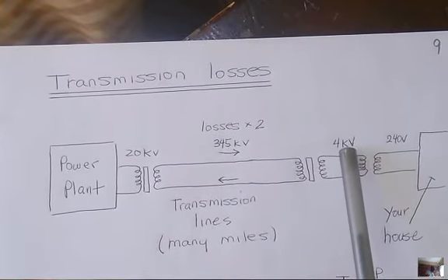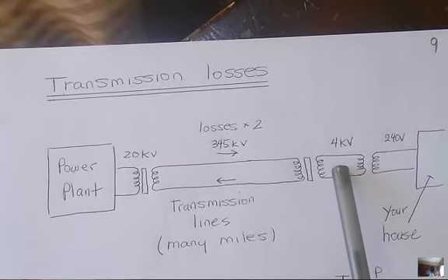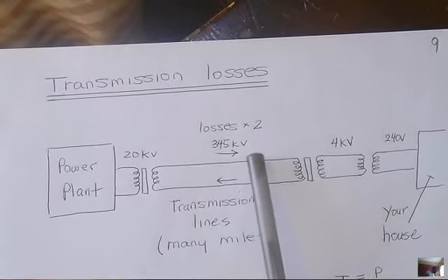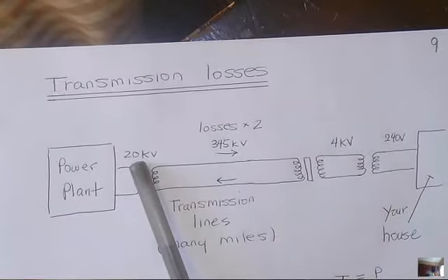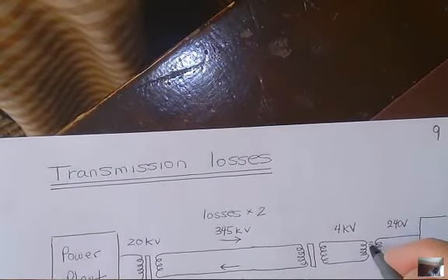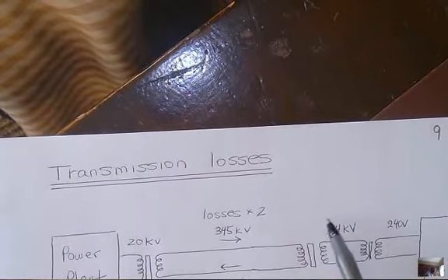This is in the town that you live in, different areas of the town. They probably have maybe 5, 6 of these in a typical Bergen County town. There's a step-down transformer that takes it from 345 kilovolts back down, even below where it started at the power plant, to 4 kilovolts. And that 4 kilovolts goes through another transformer that comes to your street. So the wires that are coming to your street are at 4 kilovolts. So this is the power lines that come into your neighborhood.